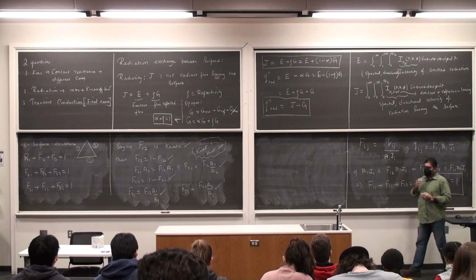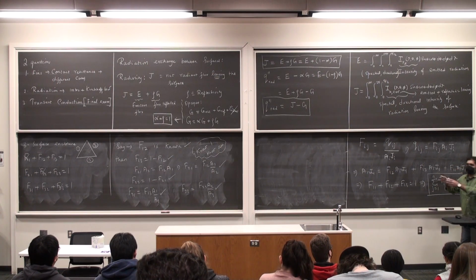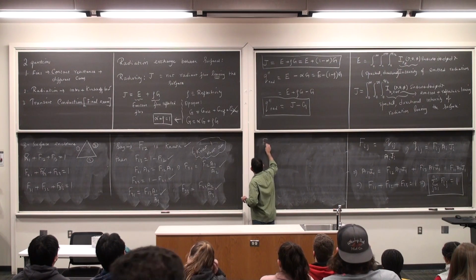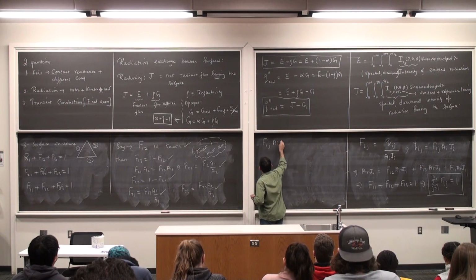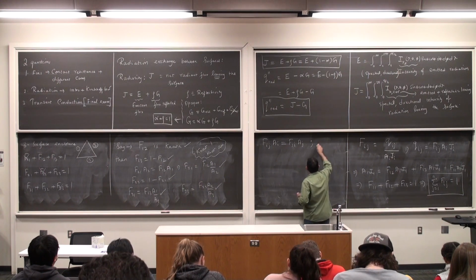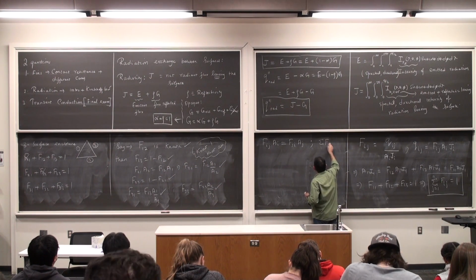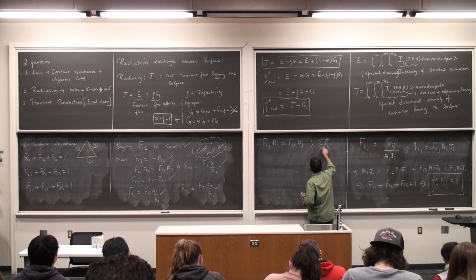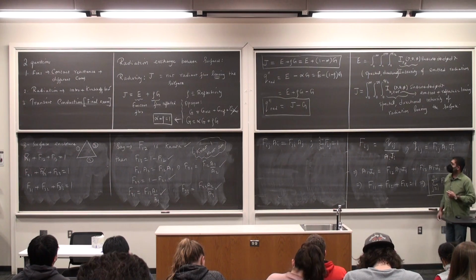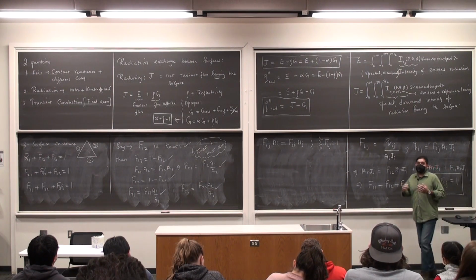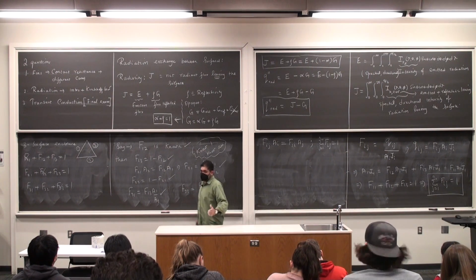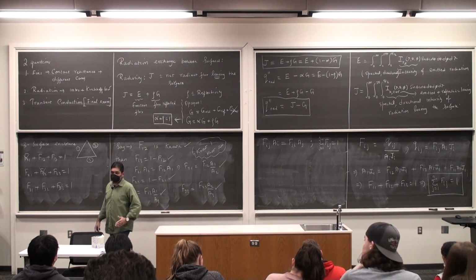So what we are going to do is we are going to make use of all of this information. The main thing that I'm going to take away from here today is the two things. Fij Ai is Fji Aj, and summation Fij over j is equal to 1. I'm going to take these two equations and we are going to create a radiative resistance network which is different from the resistance networks we've done for conduction and convection.